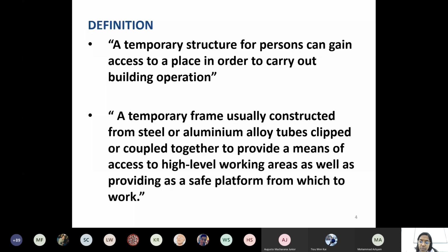Formwork is the structures, shutters, the boxes that are used for preparing your concrete column, slab. A temporary structure. Scaffolding will be the poles, all the supporting elements of formwork. It may be vertical, it may be horizontal, it may be inclined, it may be a screw, nut, bolt, tie, pin. All these things are called scaffolding elements.